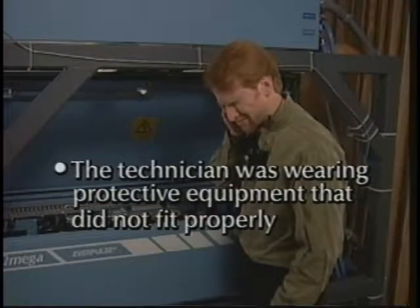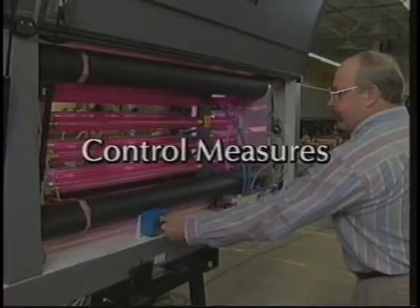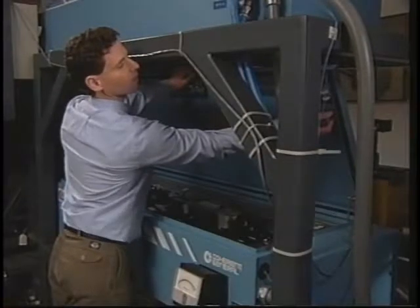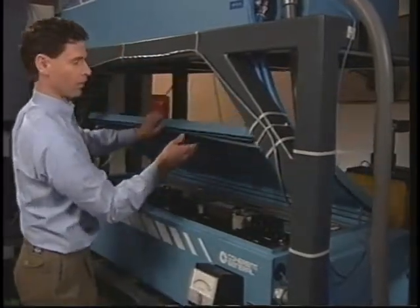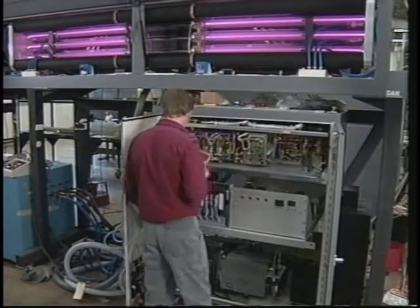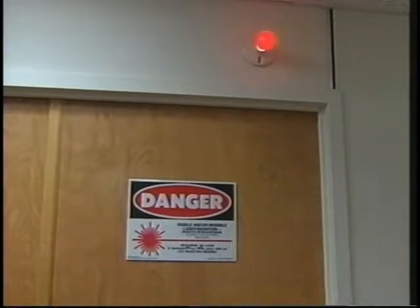It is your responsibility to make sure that your equipment fits properly. If there's a problem, see the laser safety officer before you begin working. Here are important engineering and procedural control measures for working with lasers in manufacturing. The best safeguards are protective housings and interlocks. If the laser beam and its reflections cannot be completely enclosed, other control measures must protect you.